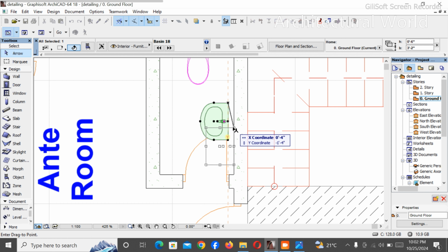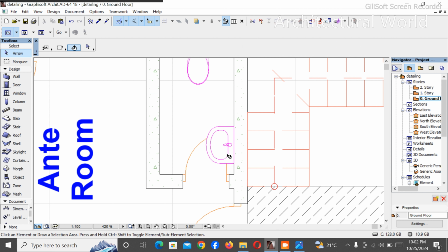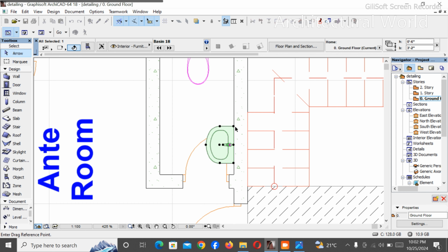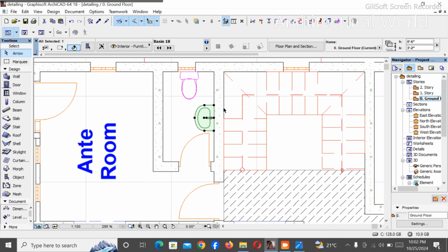You need to arrange the compartments. Now, if I place a basin here and when this door is being opened, the door is going to be constantly jamming this basin and it can't go beyond this part. So which means placing this basin here is wrong. And me taking this basin down to this part for the door to be free is wrong because I have a lot of space here to play with. So a situation like this, you need to move this basin to this part. This basin has to be moved to this part.